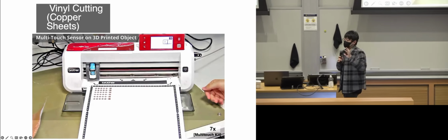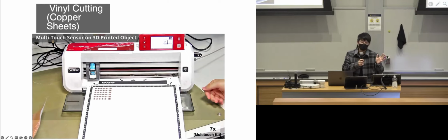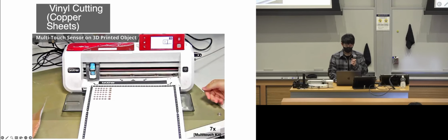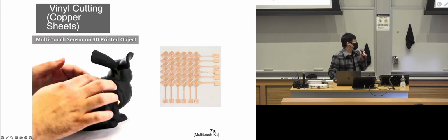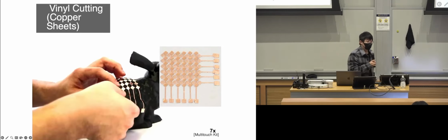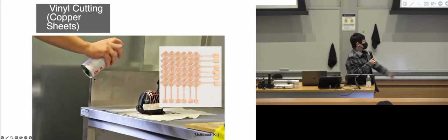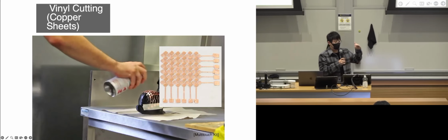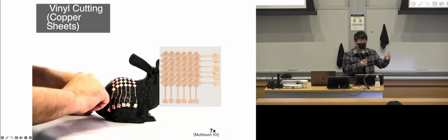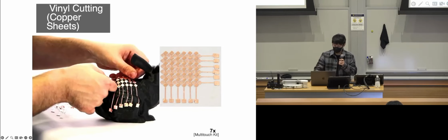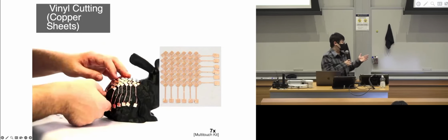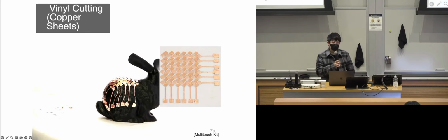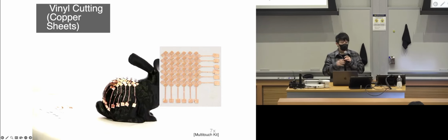You can even build almost like a flexible PCB with limited curvature with your circuit. To just show, you can use the Stanford Bunny, which everyone loves to use as a show-off for geometry complexity. These types of things can actually be applied onto more curved or convex surfaces, such as the Stanford Bunny. Of course, it takes some manual work, but compared to a 1 to 2 week turnaround time on PCB manufacturing, this is much faster as a design iteration tool.